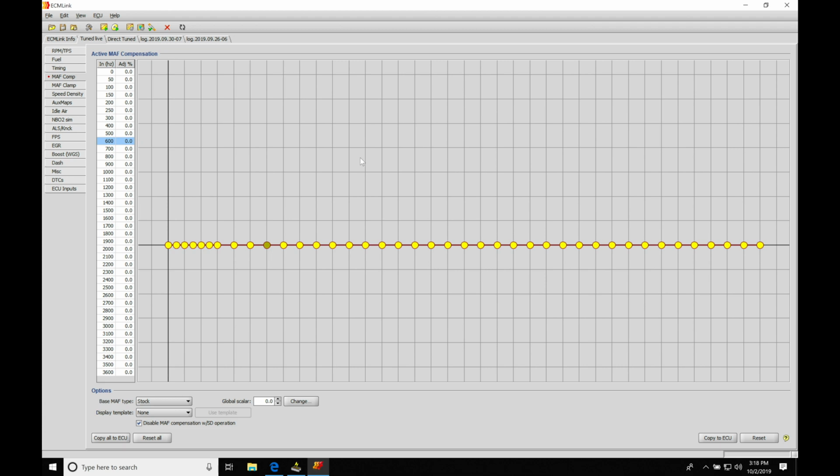And we'll find we have 3 different zones for the long-term fuel trim. We're going to have a low, a mid, and a high. So depending on where we're operating, typically idle and very, very light throttle is going to be low. A little bit more throttle is going to be the mid. And then the high is going to be right before we transition over into open loop at the very high throttle angles or higher load. Let's take a look at a data log so we can make sense of this and how this is going to work in my data log.